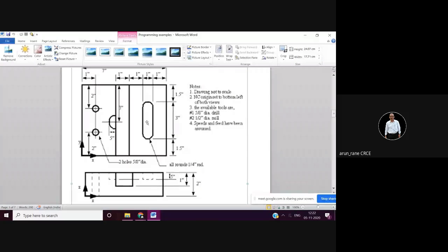Now you have to plunge the cutter slowly down. So it will be G01 Z minus, sorry, not minus. This is what happens. So Z 1.5, this height 1.5, because this depth is 0.5. So G01 Z 1.5. Then now you again do it like this, G42. The cutter will come from here, touch here, and go like this. So it is on the right hand side. So G01 Z 1.5, G41.